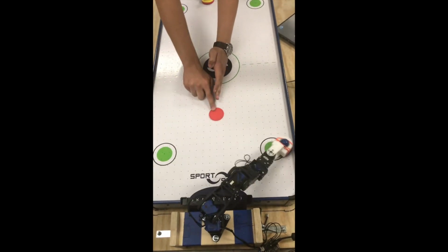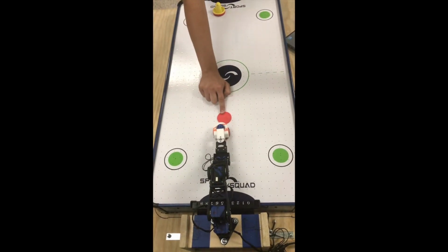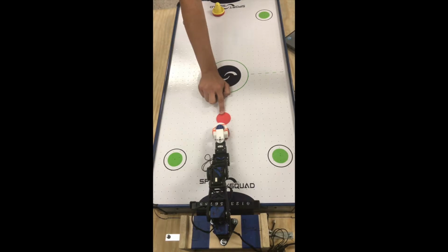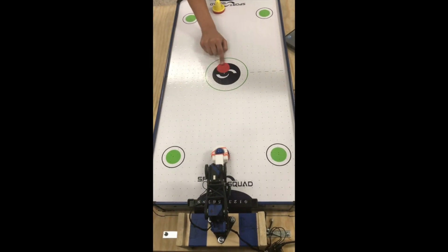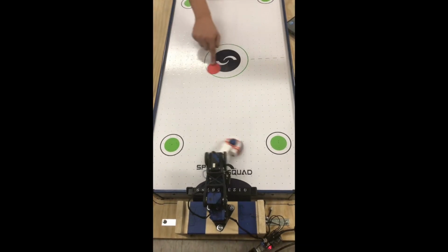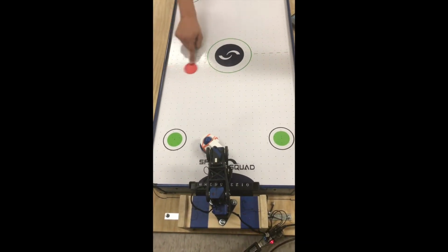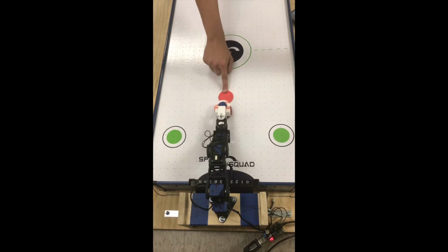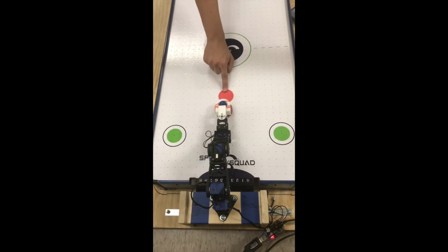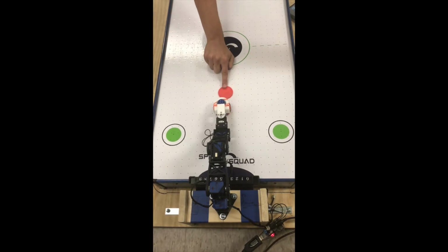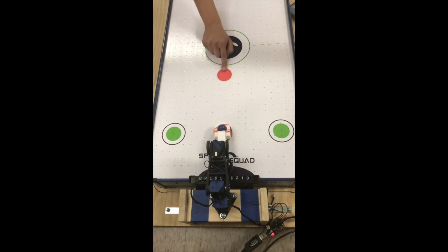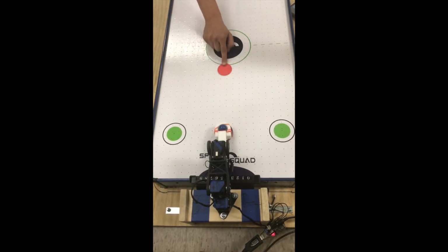We use inverse kinematics to calculate the necessary Rex arm joint configurations to place the striker in the desired position. When the puck is far away from the goal, the Rex arm moves along a radius close to the goal. Once the puck passes a distance threshold and gets closer to the goal, the Rex arm moves along a radius farther from the goal. The transition between the radii of motion is the striking action for the Rex arm.